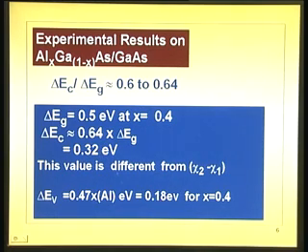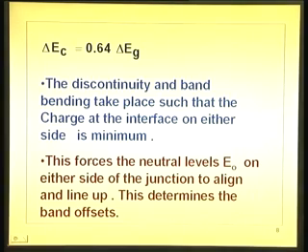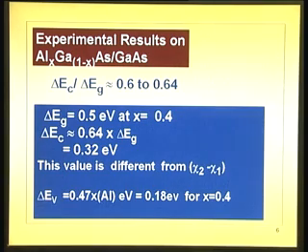It is like saying the neutral level in gallium arsenide is 1/3 of Eg above the valence band, and in silicon also 1/3 Eg above the valence band. But if you take indium phosphide, there is a different story altogether. The neutral level is not at 1/3 Eg above the valence band. So this particular term will be different for different systems, therefore, the AlGaAs system.